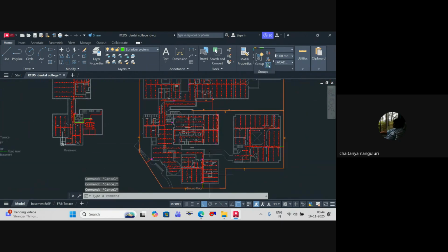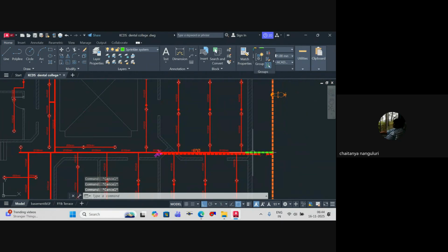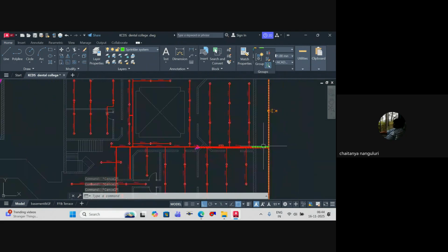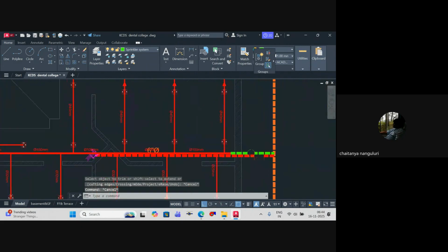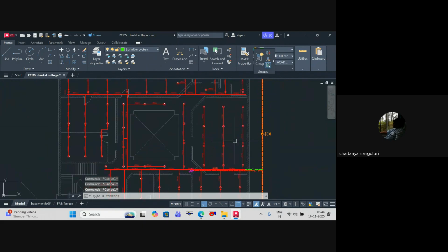So wherever we have these external ones on the ground, what we have to show is an alarm valve. Understood? We will have an alarm valve whenever you have a sprinkler system. It's mandatory to have an alarm valve because in this zone, if there's a sprinkler, it should ring so that everyone will be notified that the sprinkler got broken. Am I clear?